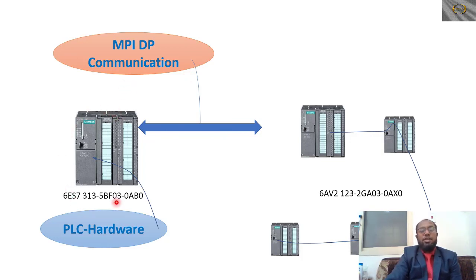Then the wet station receives its signal that it wants to do its operational work. Then it gives a command signal to the wet station PLC. If the wet station PLC has some issue or some alarm, then it gives a feedback signal to the master station PLC. Then the master station PLC cannot operate or cannot send the signal to the dry station PLC. The wet station is not ready for the operation, so it stops the work.